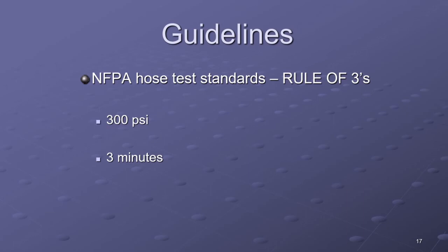Why would we have to limit it? I don't know why they did in the beginning. But I think an important piece here is generally our hose is rated at 300 PSI. So if you're looking at a hose lay that needs 450 PSI to pump it, you may be outside of tolerance. It may not work.